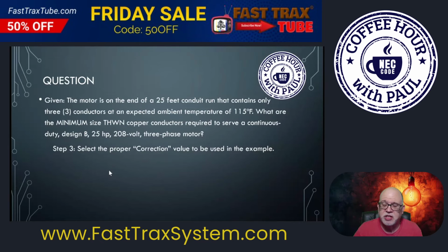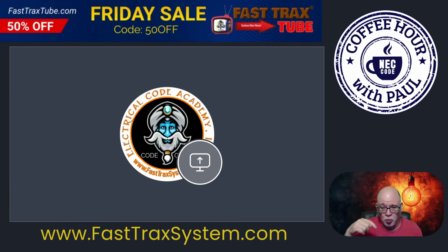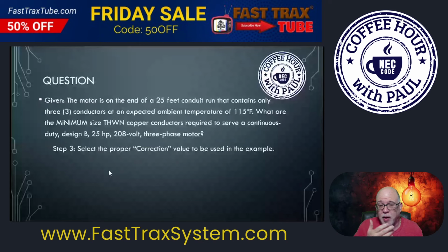It's still a condition of use that we have to take care of. Now, notice we don't have more than 3 current carrying conductors, so we don't have to worry about that in our equation, but it would work the same way if it was in the equation. Same way that we're going to work this one. It's just you would have both in play rather than just one item in play.